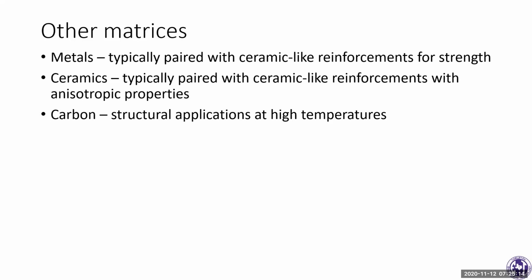Metal matrix composites have matrices that are metallic. Aluminum is often used. Common reinforcements are short fibers made from ceramic, like silicon carbide. Ceramic matrix composites have ceramic materials as their matrices, such as carbon, silicon carbide, alumina, and mullite. Their reinforcements are often made from the same material, but in short fiber form.